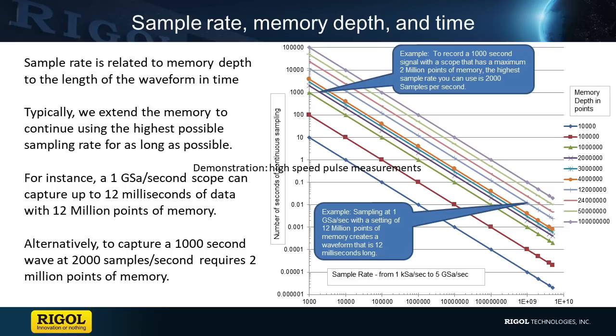So that gives you the clearest image of what's happening in high speed voltage space. But all digital scopes have a certain amount of memory too. Ours tend to have quite a bit, but even with the 12 million points of memory that's standard in these instruments, if you're sampling at a gigasample with 12 million points, how long is that in time? Well, 12 million times 1/1000th of a microsecond is 12 milliseconds. So you can look at 12 milliseconds in time with a super high quality picture, sampling 1 billion times a second, getting all that data, converting it, and getting it onto the display.